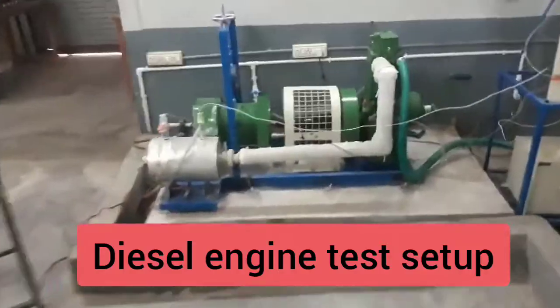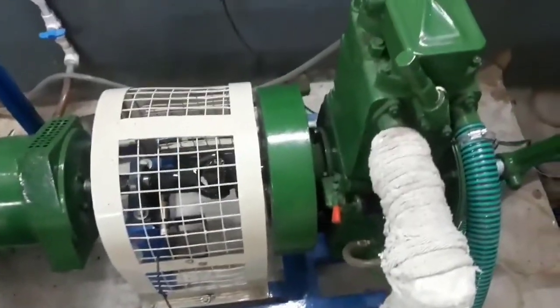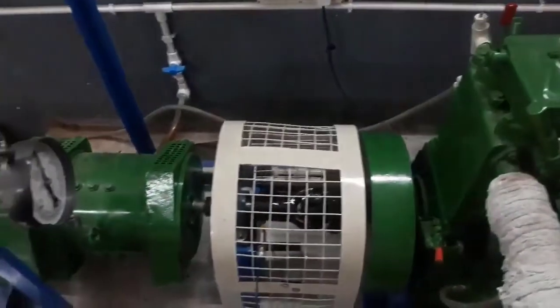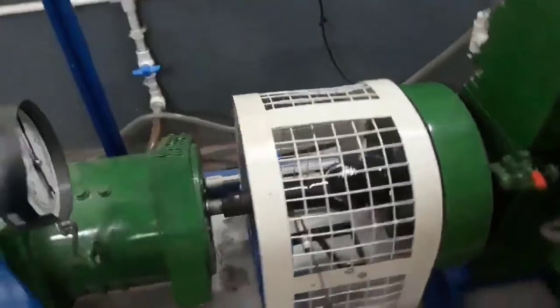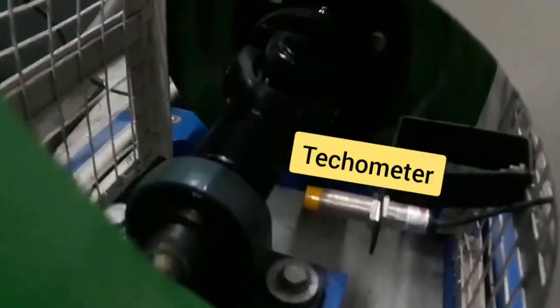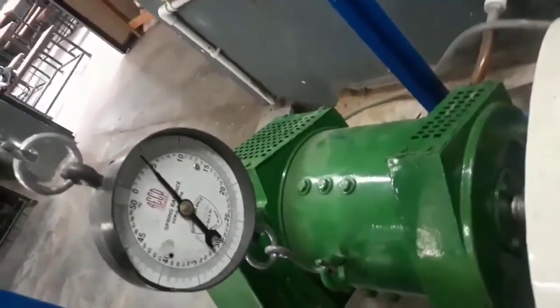So this is your diesel engine test setup for performing the Willians line method. This is your engine, which is a single cylinder 4-stroke diesel engine, connected with the electrical dynamometer. This dynamometer is connected with a coupling. Here one tachometer is provided to measure the engine speed in terms of RPM. Now this is your U joint, which is coupled with an electronic dynamometer.